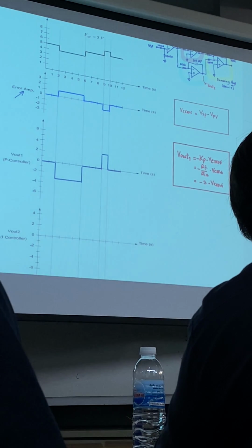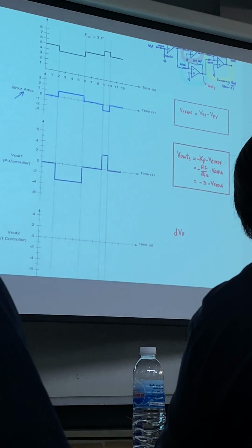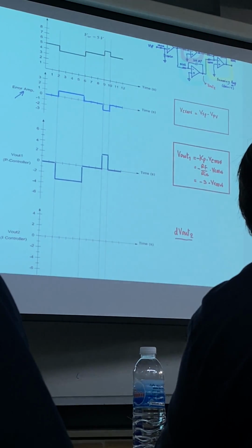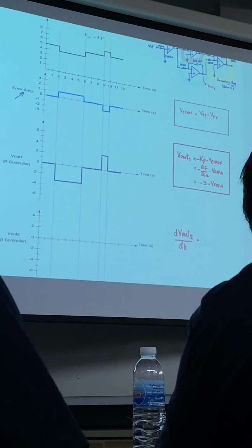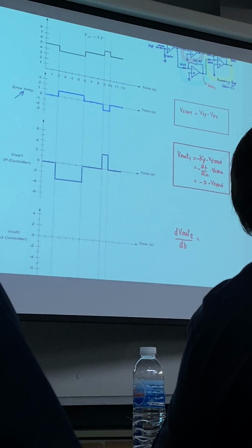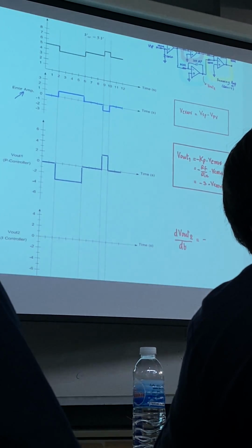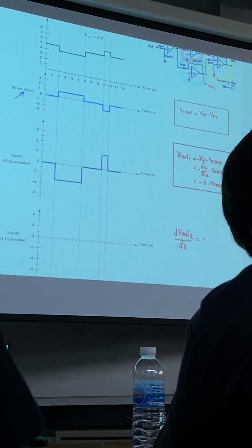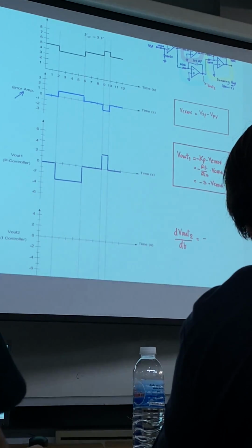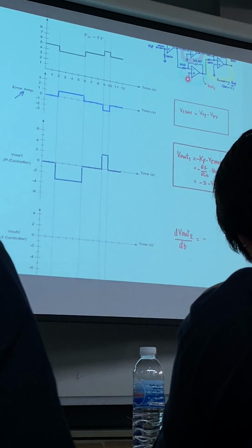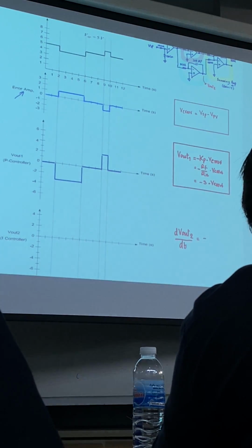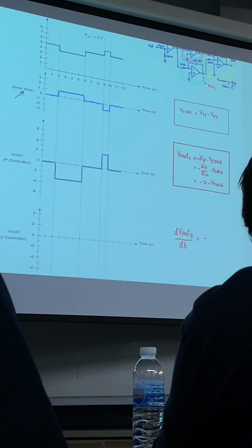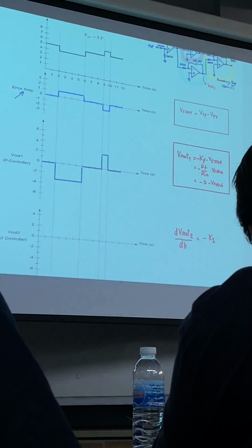So I can derive dVout/dt is equal to one factor, but this factor has to make a negative voltage because the input of the circuit is at the inverting input, so you have a minus here. Minus Ki multiplied with V.